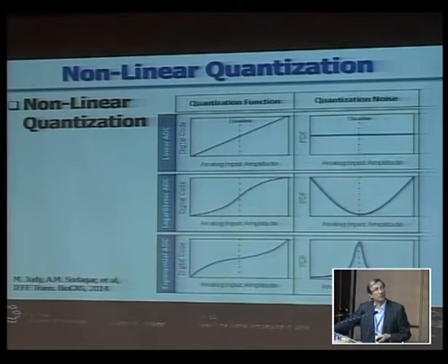Let me skip this slide by just talking about two halves of a characteristic that are required for the processing of a neural signal. Supposing that the signal is located around a baseline, which is usually 0, because the LFP, low frequency contents of the signal and also the DC component, is already rejected when you are processing the signal.